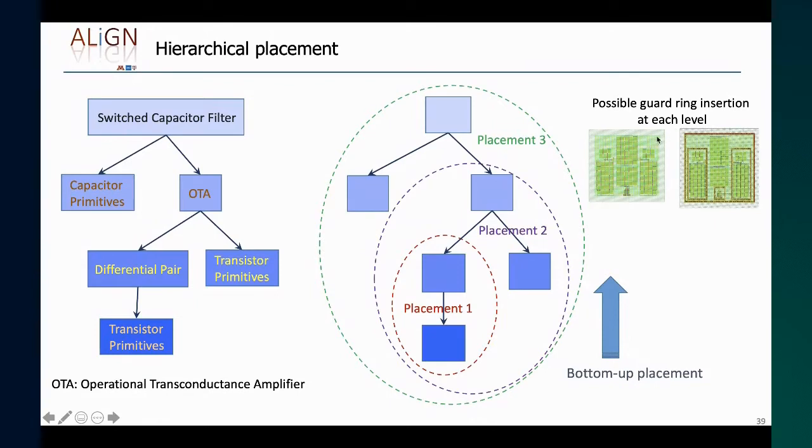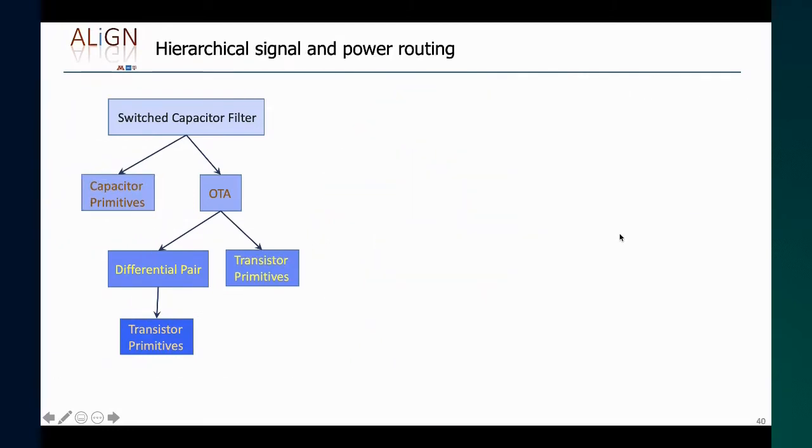In some cases, our blocks may require a guard ring, which is a noise prevention methodology. So if the block is noise sensitive, we can actually incorporate that as well into the layout before block assembly.